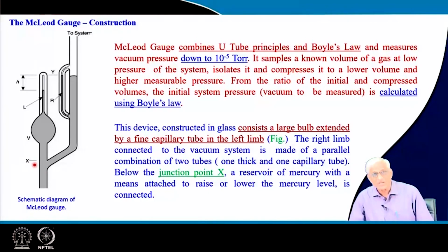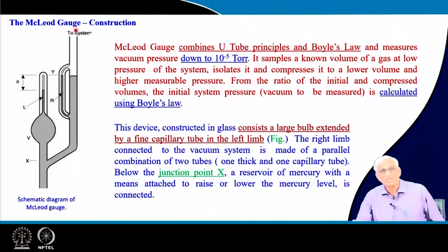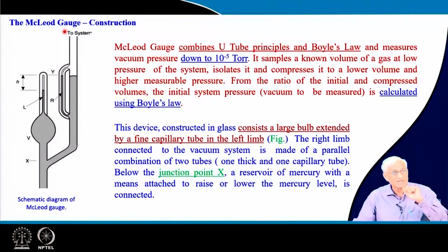At the time of isolation, at that instant, whatever the vacuum is, that is what we are measuring. Then we need to do some manipulations to make measurements, which we will see now. By that time, if the vacuum level changes, we are not responsible for it. We are measuring that instant when this got isolated. At that time, if you connect another secondary gauge, whatever the reading of the secondary gauge is, you take and keep it. That reading will be calibrated against the vacuum that we are going to compute.